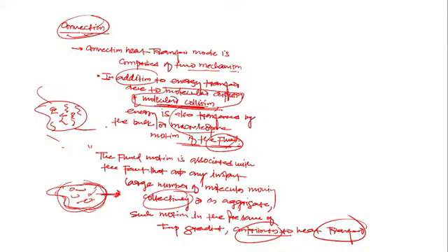Every individual has its own contribution. Yes or no? That's why I'm saying you can imagine it like that, so that you can correlate what is the bulk motion and what is the aggregate. Because the molecules in the aggregate, meaning the molecules are the persons and the aggregate is the whole swimming pool. So molecules in the aggregate retain their random motion, and hence the total heat transfer, and here I am talking about total movement, is then due to a superposition of energy transport by random motion of the molecules and by bulk motion of the fluid. Yes or no?